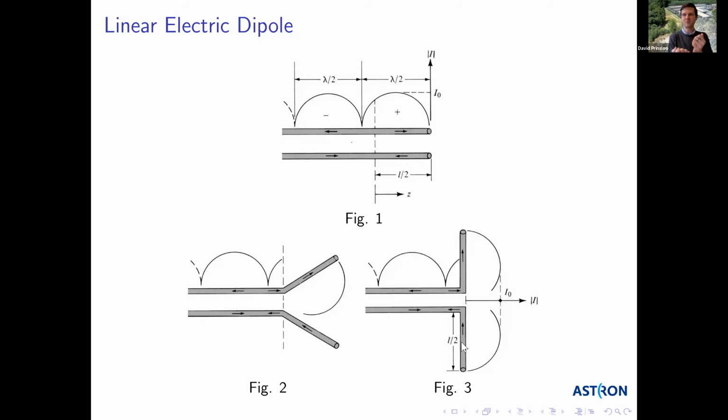That's not a very simple thing to just explain as sinusoidal. One of the best ways to visualize that it could be sinusoidal is to see it as an open-ended transmission line, which we know has standing waves on it. And if you bend it open, that same sinusoidal nature is maintained on the dipole antenna.